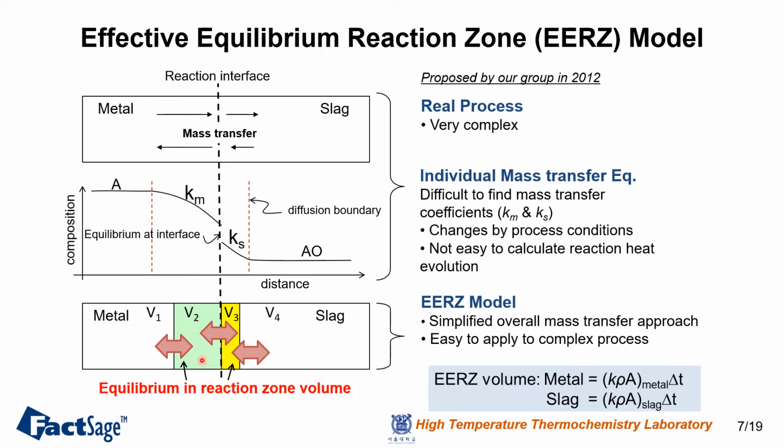So whenever you have a chemical reaction at the interface between the slag and the metal, for example, then a certain amount of heat can be generated or a certain amount of heat can be sunk, depending on whether it is an endothermic reaction or an exothermic reaction. Because we are using the accurate thermodynamic database, we can track all the heat amounts during this operation,